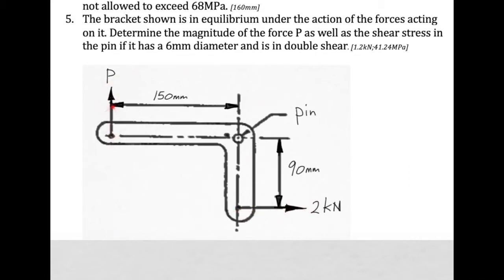So we're going to apply a force in a vertical direction. And via this bell crank, we are going to get out a force which we could then use elsewhere in our mechanism in another direction. At the same time, we can also, by means of leverage, change the magnitude of that force by having varying lengths over here.